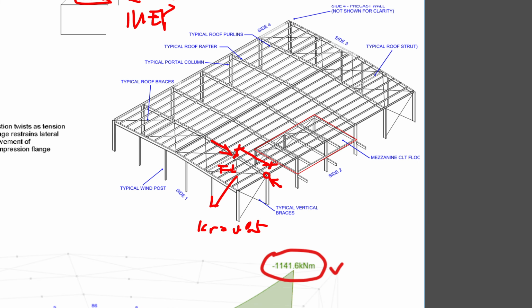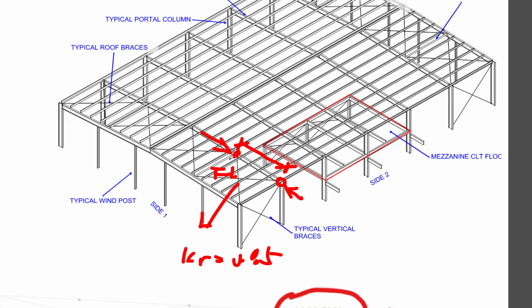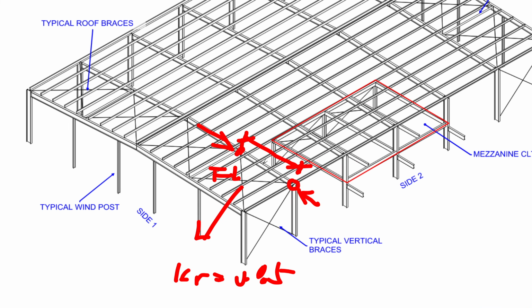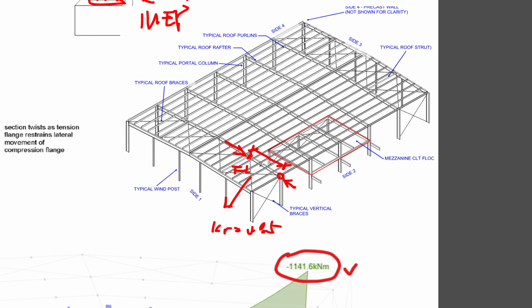Which means that if I've got really good boundary conditions on both ends of my segment, I can reduce my length, so make my column or my beam less squashy. That means I can reduce about 15% of my segment length. So the LEY is the segment length times 0.85.